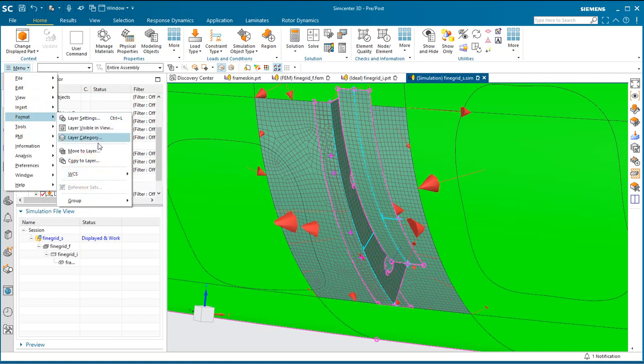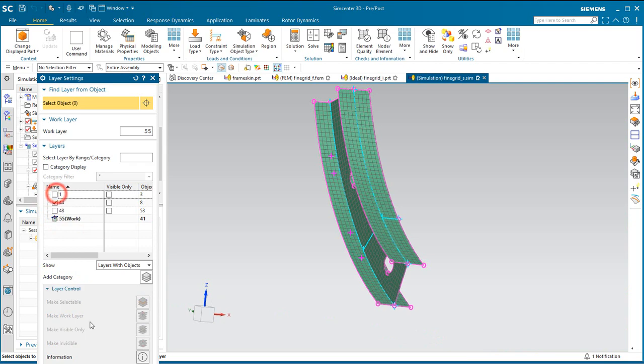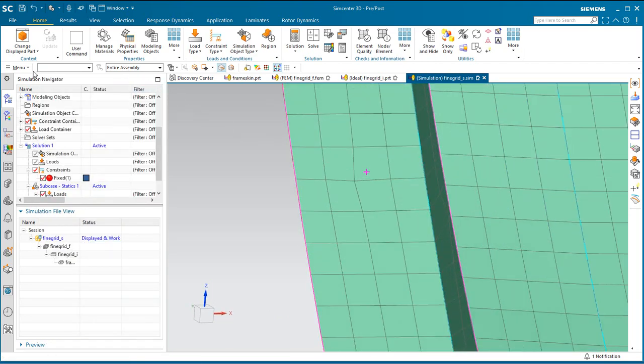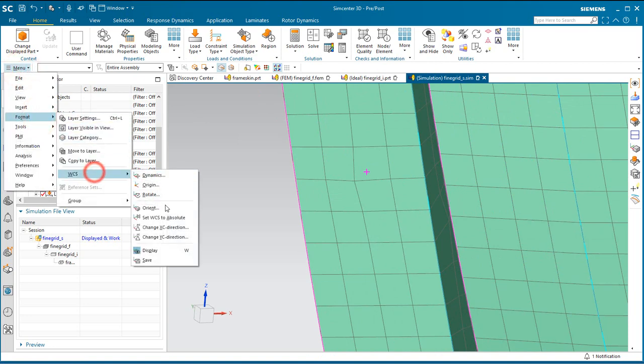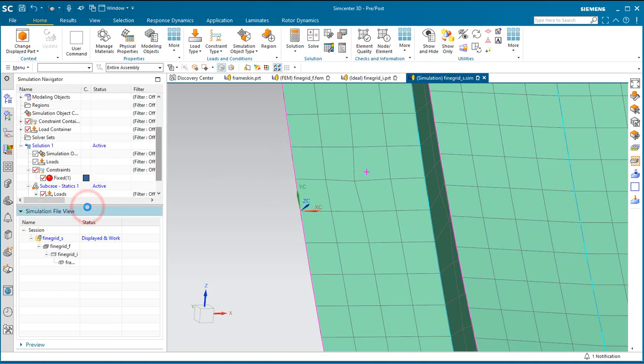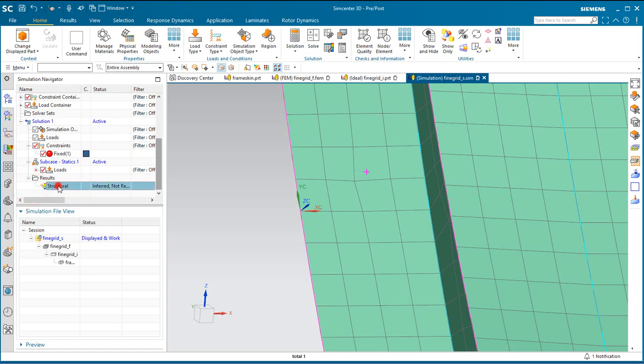And then so that we can see those loads in the plane of that coupon, what we'll do is we'll locate a coordinate system around that group of elements. So I'll orient it basically in the plane of those elements. And I'll do that selecting an origin and then an X point on the x-axis and a y point for the y-axis. So now that coordinate system is in the plane of the coupon.